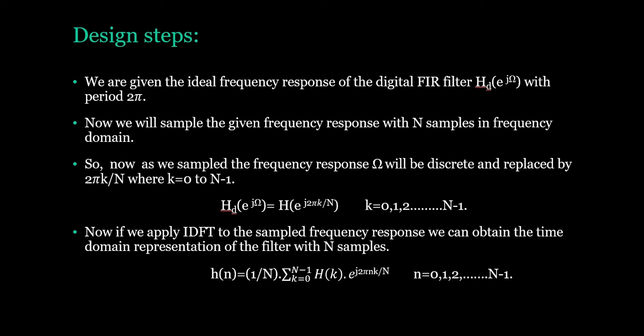And if we apply IDFT to the sampled frequency response, we can obtain the time domain representation of the filter with N samples. And this is the equation for the time domain representation of the filter, and n runs from 0 to N minus 1 as it will be having N samples.